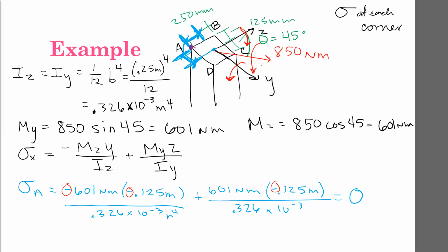They're equal, which means the line about which the moment occurs is the same as the line that's my neutral axis. Good. Point C must also be on that neutral axis, which means I don't even have to calculate it. You know that sigma C is going to be equal to 0. And further, I know that B and D are going to be equal and opposite, right? Because this is a square and across the diagonal is my neutral axis. So B and D will be equal and opposite. So let's calculate one of them, and then we'll know the magnitude of the other.